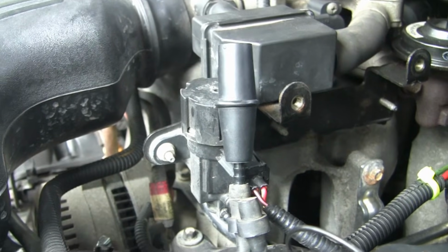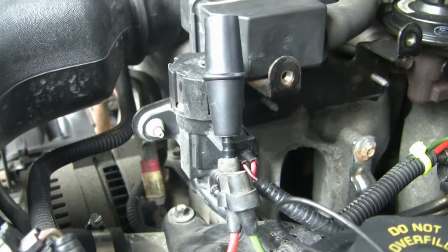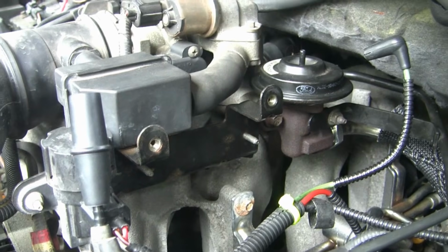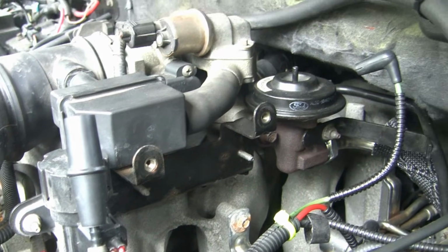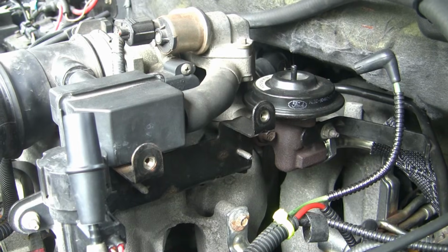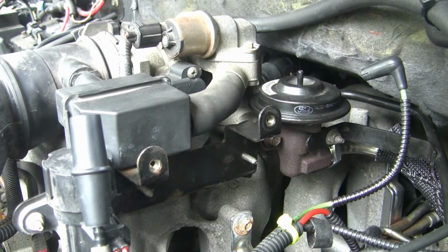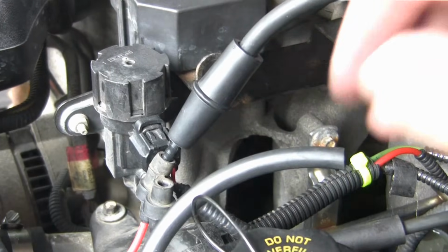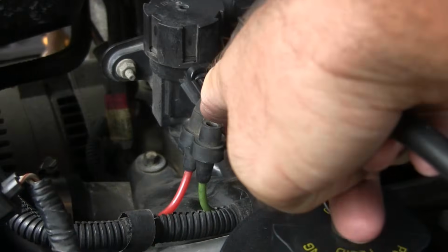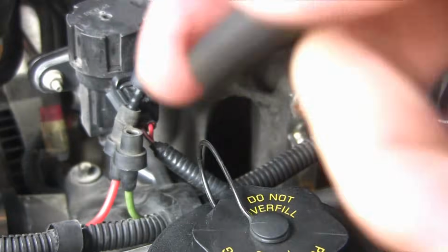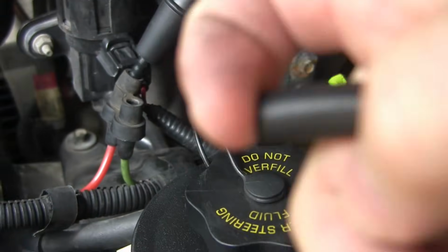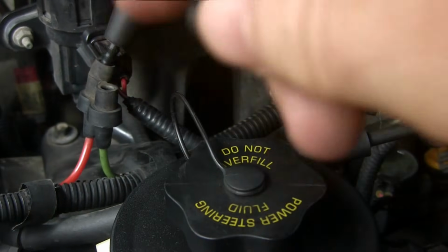Okay, I'm going to put the camera down, and I'm going to go ahead and fit this hose in here and then start the engine and apply the vacuum. We can't start the engine with the vacuum applied because it probably won't start if its EGR valve is functioning properly. Be right back. Okay, the engine's running. We've got the vacuum hooked into our source here at the regulator, and I can feel the suction vacuum when I get my finger in it.